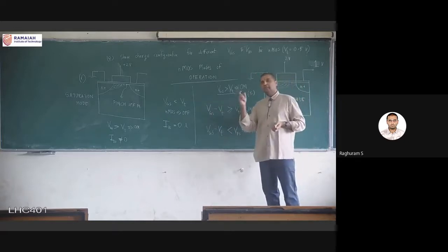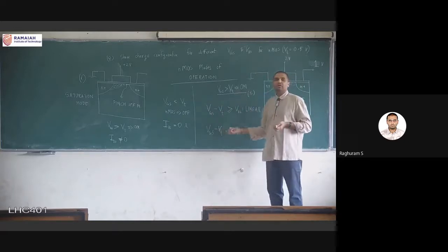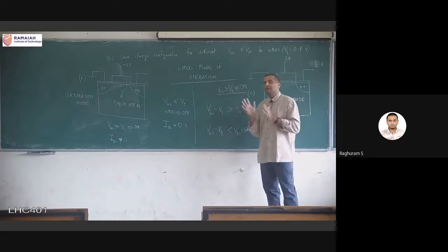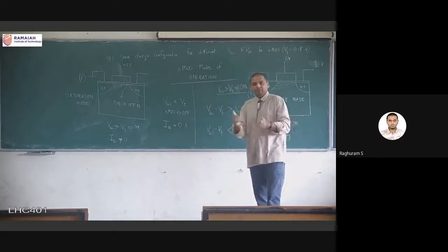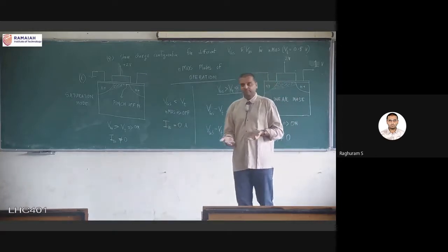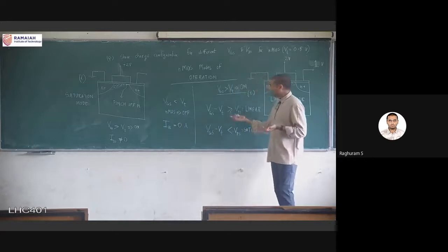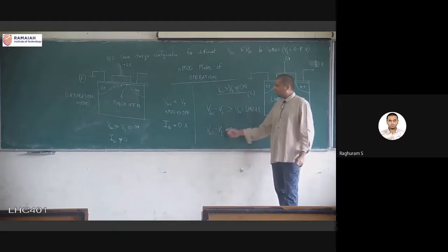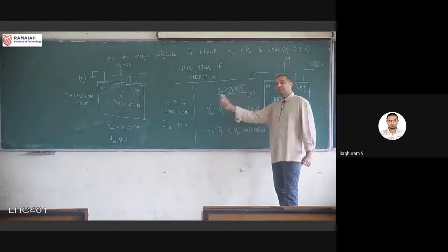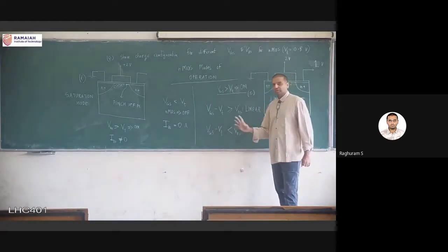The slight modification, we will just convert it for saturation. So it's not going to be two separate derivations, but the expression is different. What that means is, whenever you are going to calculate the current, which is what we will be doing, we have to find out what is the region of operation. Directly, if you put the current and calculate, you will get an answer, but it might not be correct because there are two separate regions and two separate equations for the current.